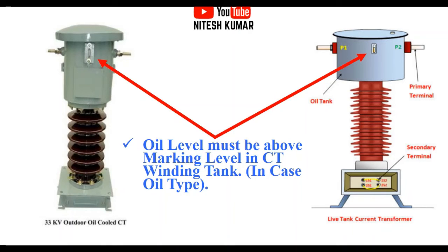Except this point, you have to take care of all the points, okay. So on that site, what happened was that the oil level was low, so for cooling purposes there was no oil, and continuously that CT was charged. So what happened, there was a heating effect in the winding, and the insulation paper used in the winding got burnt, and in such a way the CT blasted. Okay, so this is the thing I am just sharing with you.